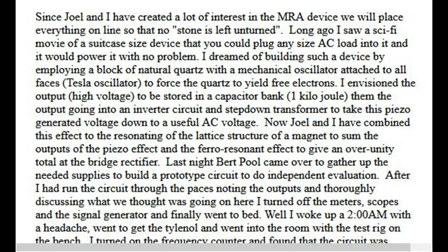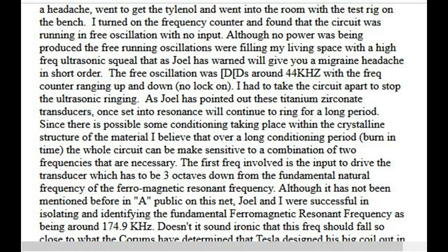Well, I woke up at 2:00 a.m. with a headache, went to get the Tylenol and went into the room with the test rig on the bench. I turned on the frequency counter and found that the circuit was running in free oscillation with no input. Although no power was being produced, the free running oscillations were filling my living space with a high frequency ultrasonic squeal that, as Joel has warned, will give you a migraine headache in short order. The free oscillation was around 44 kHz with the frequency counter ranging up and down, no lock on. I had to take the circuit apart to stop the ultrasonic ringing.